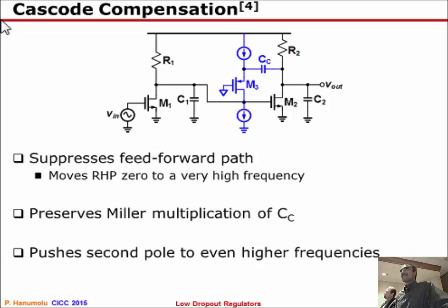Towards the end, you gave a couple examples of that, swapping who's dominant pole. And you want to comment on the transient performance capabilities. Yeah, so if you have output pole dominant, there are two ways to address load transients, right?